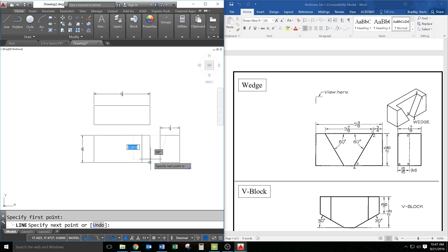So I now need to turn ortho off. And what I need to do is look. If I'm going straight down, the angle that you see to the right of my cursor says 90 degrees. Here, the angle says 180 degrees. Well, mine has to be 60 degrees from the 180, so you watch that go down. So this basically needs to go to 120. I'm going to draw a line that's longer, a line that's 5, and then I hit tab. I type in 120 for 120 degrees, and I hit enter.